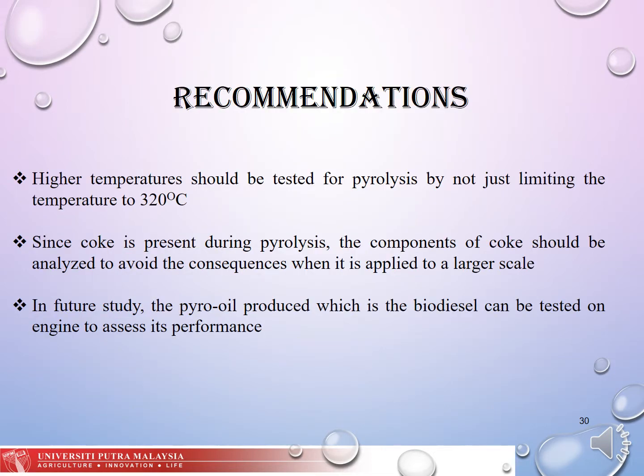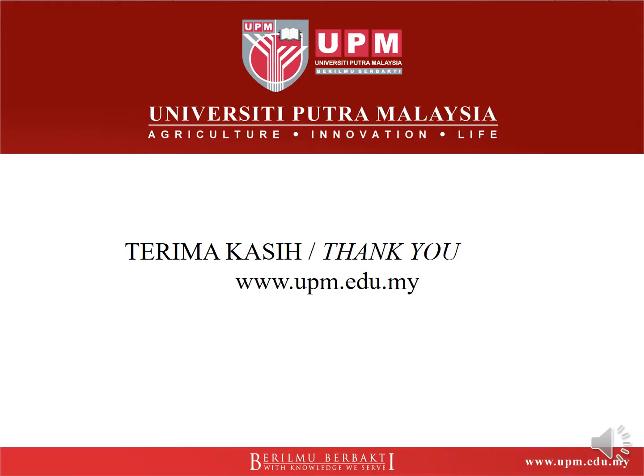So my recommendations are that higher temperatures should be tested for the pyrolysis, not just limiting the temperature to 320. Besides, since coke is produced during the pyrolysis, which is the solid yield, the components of the coke should be analyzed as well by sending it for SEM EDX testing to know the components in it, to avoid consequences when it's applied on a larger scale. In future study, the pyro oil produced, which is the biodiesel, can be tested on an engine to assess its performance. So that's all from me.